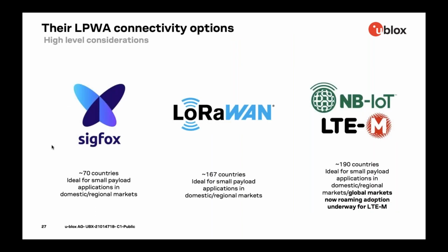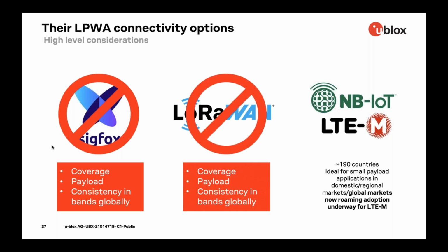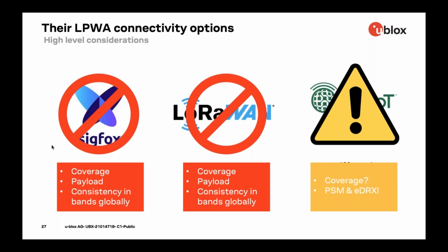So when we start thinking about, great, I'm now going to design this device and need to sell it around the world, similarly, this isn't an application necessarily right for Sigfox, whereas maybe an environmental monitoring solution across Europe would be. So the strategy is let's find something that will work globally in this instance. Similarly, LoRaWAN wouldn't necessarily be right for similar reasons. And then the low power cellular variants aren't quite right. They're almost there. If we had the patchwork of roaming available globally from us or anyone who provides a solution with a SIM in, then this would be a more widespread solution, and it is coming, but it's taking time. So again, how do we get the low power variant? How do we make this kind of perfect device? And as Nick mentioned, there are some challenges from that perspective.